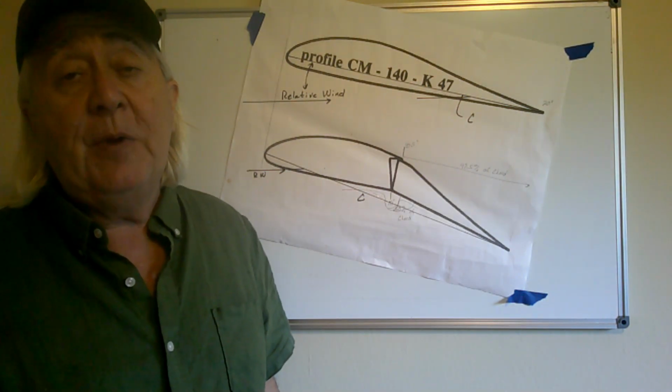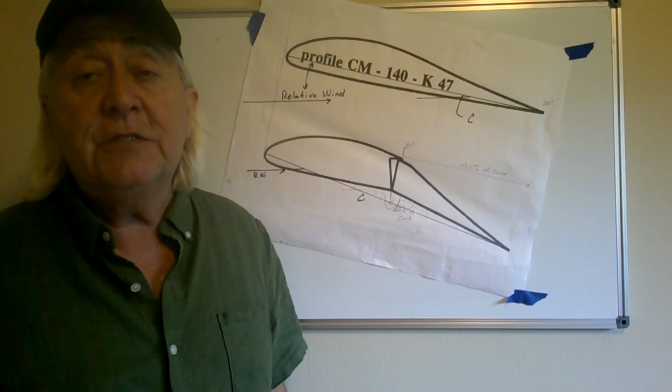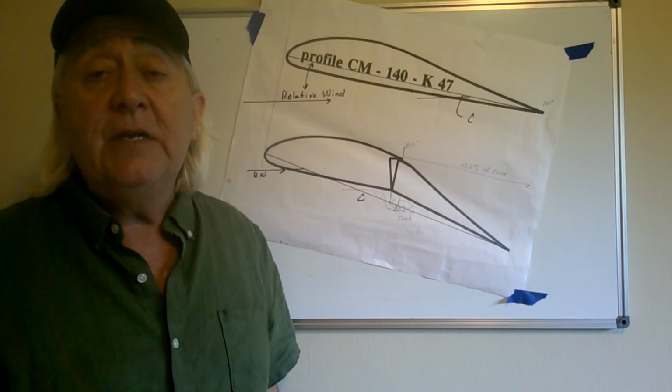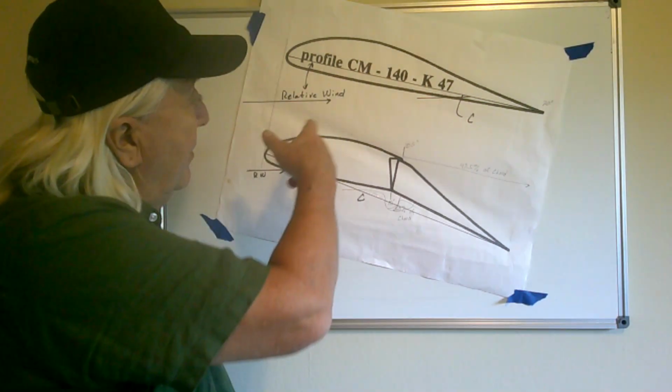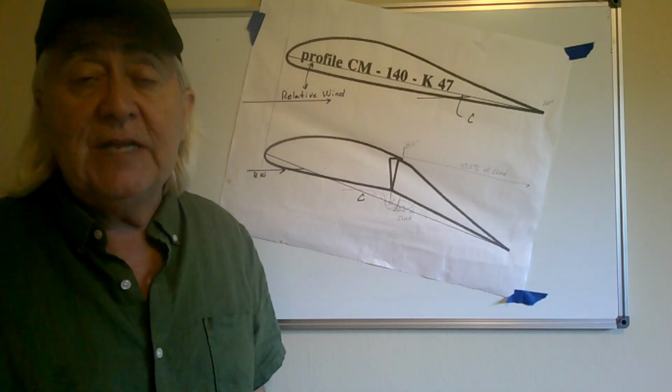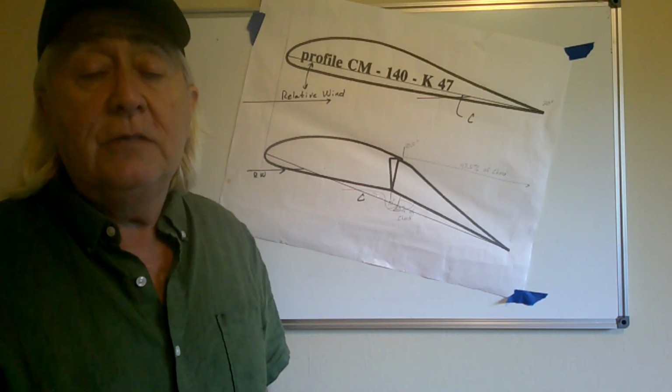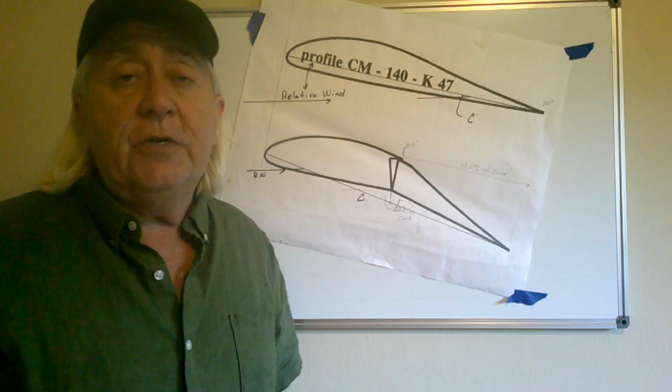It just wasn't time to do all of that. Even if he had gotten the flap up instantly, he still wouldn't have recovered because he's going to have to regain flying speed until his relative wind is oriented where he's at a positive angle of attack below stall. So, unrecoverable.